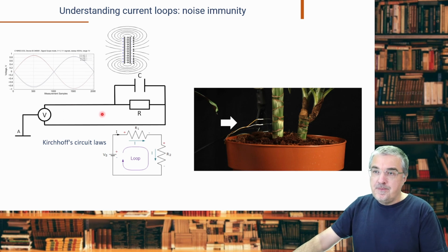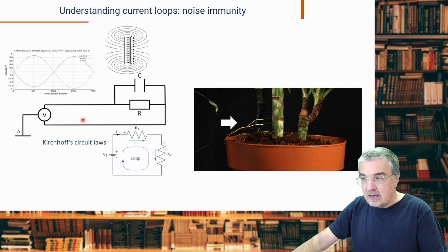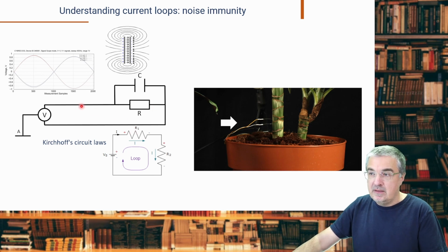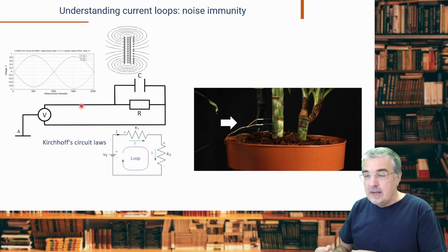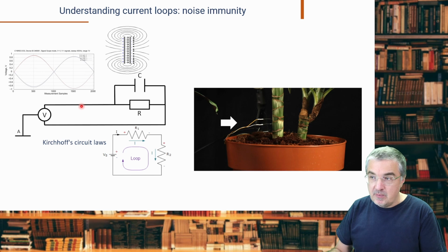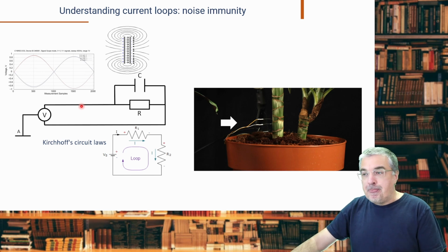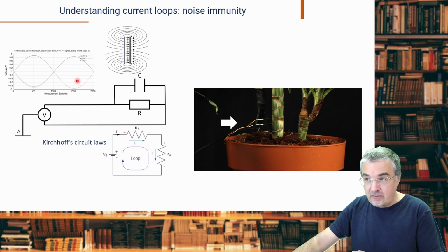And it seems here it's only one loop. By Kirchhoff's law, this loop is independent, for instance, of the length of the wires, so it's noise immune. So it's a good point. In measurements, we frequently use these current loops for sensing remote objects because of this noise immunity. And we receive a number of questions regarding this noise immunity: why, for instance, in some cases it doesn't work.